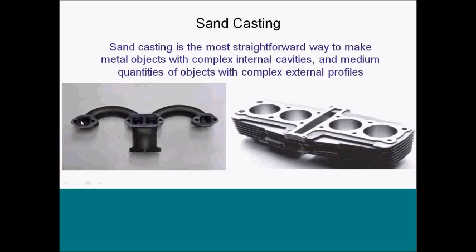And so the hot exhaust gases exit out of the head of the engine through these ports and are collected together and go down and flow on into the exhaust system of your car and your muffler and your catalytic converter. And this geometry has quite a complex shape, and it's got a lot of internal cavities here for the exhaust gases to flow through, and it also gets quite hot, so the material we choose has to be resistant to those high temperatures, and there's also an exhaust system hanging off this, and so it has to be reasonably structural.